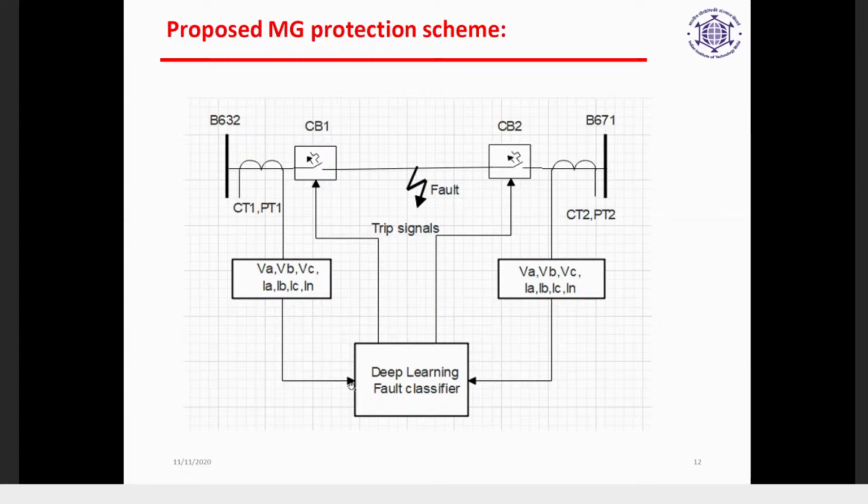If there is any fault in the system, we first identify what kind of fault it is, and then where in between the faults are located. Based on that, we can give a trip signal. We can trip one of the phases if it is just a single line to ground fault. If there are two phases, we can trip two of the phases, and if there's a three-phase fault, of course, then this line is not operational at all, and you have to remove all three phases.